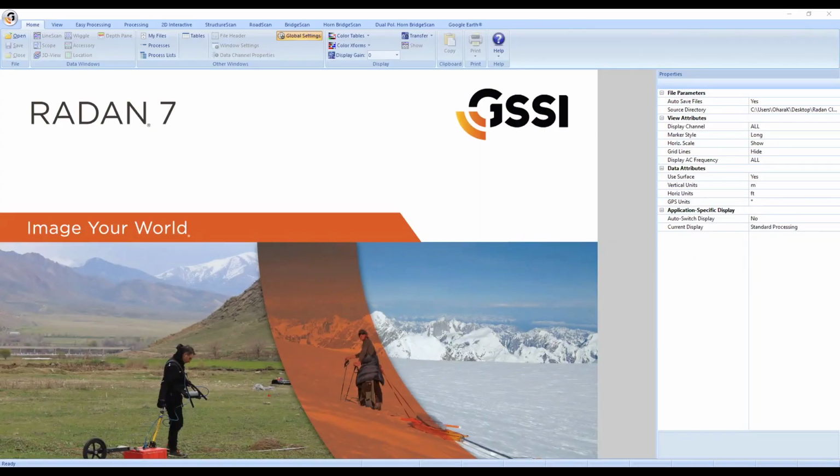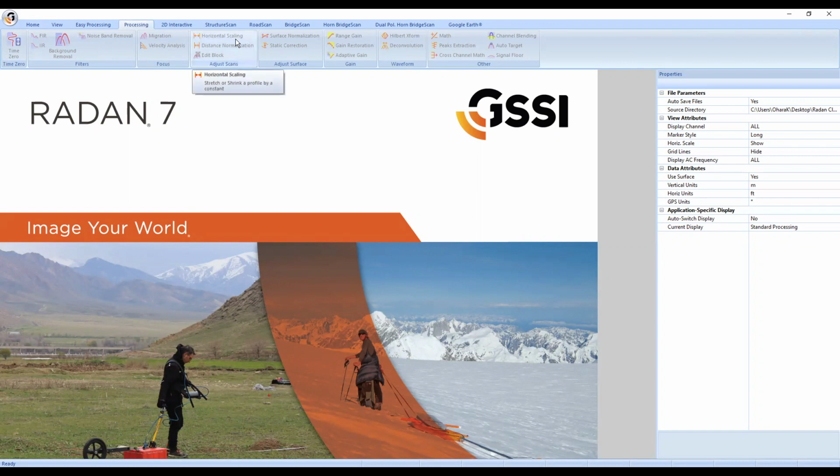Foundational theory of GPR, and then we moved into our individual 2D processes. We went through most of the processes in the processing pane yesterday, starting with horizontal scaling, distance normalization, and surface normalization, and then moving into processes like edit block, and then the most commonly used processes, which include time zero, our filters, IIR, FIR, background, and noise band, as well as the gain options at our disposal, and migration. We're going to be using a lot of those later processes as we start to explore 3D grids today.